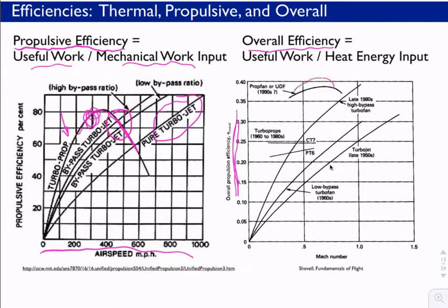This does give a little kudos to this idea of the ducted fan concept. Really, this is 1990s. It sort of started in the 1980s. That we'll look at in one of the last slides. But so what we're seeing is sort of typical in our high bypass. This diagram is from Cheval's book, which is at least the version I have is a little dated at this point. But you're talking about efficiencies from chemical to useful work of about 35%, which would be a good car engine, would be an Atkinson cycle in a car engine, something like that.